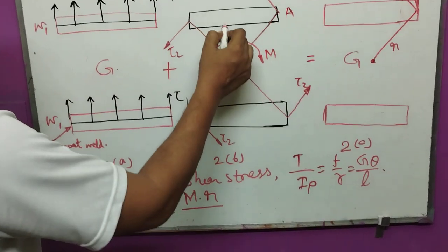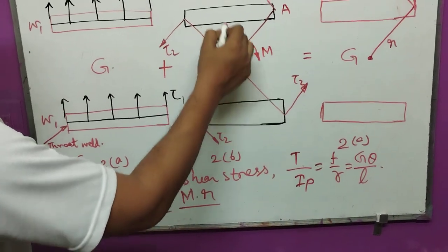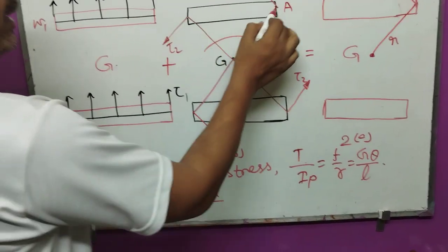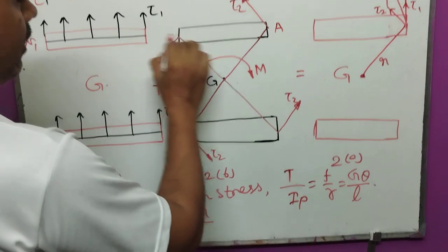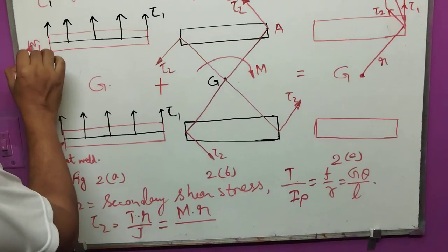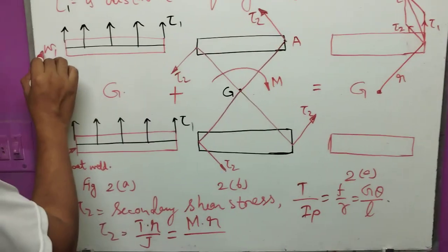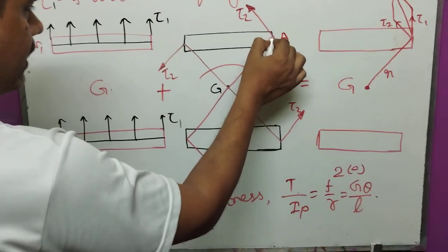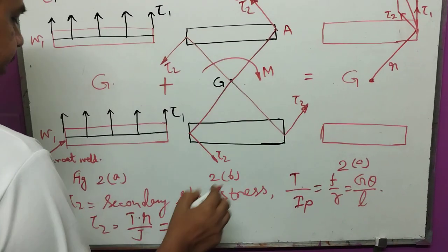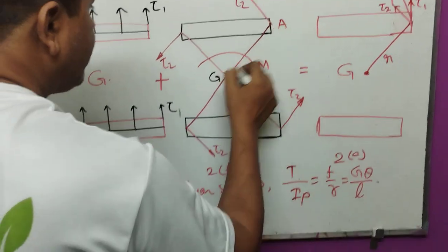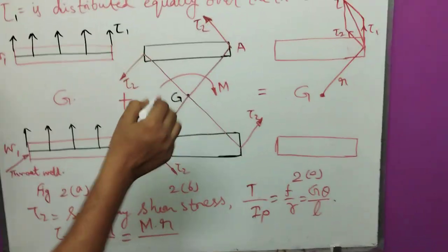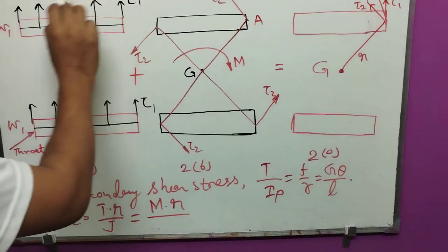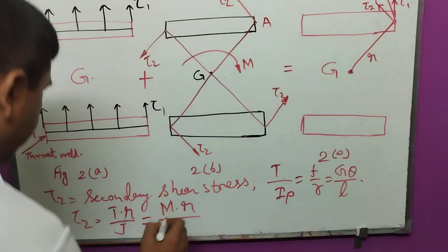The minimum distance gives a smaller value of the turning moment. Therefore, we apply the maximum distance, which is to the center of the fillet weld W1, whose area is A. This value is R1. R is the maximum radius, which applies the maximum torque for tearing the fillet weld.